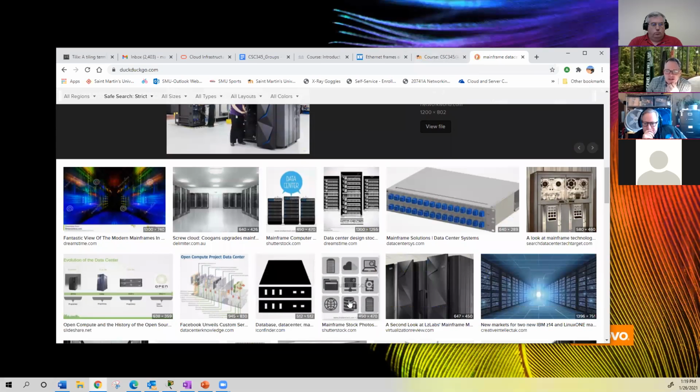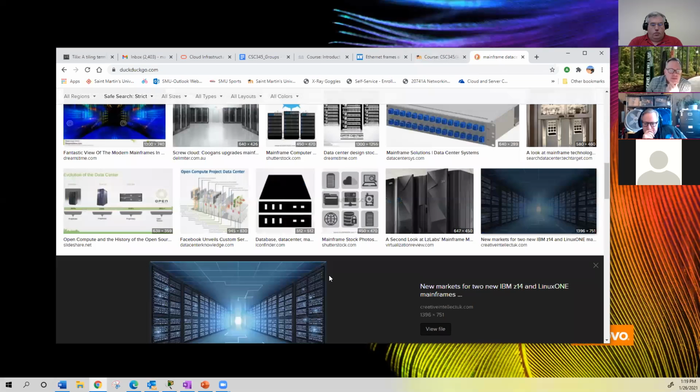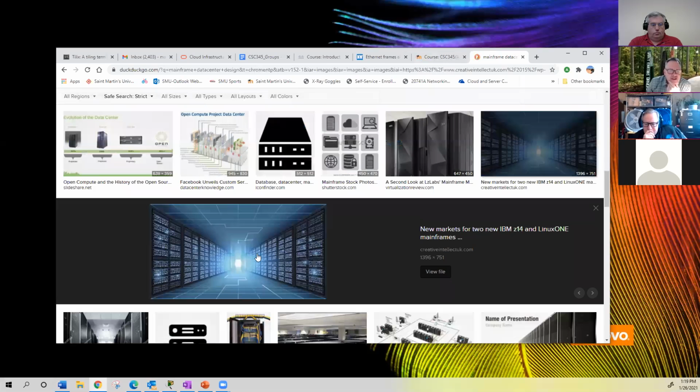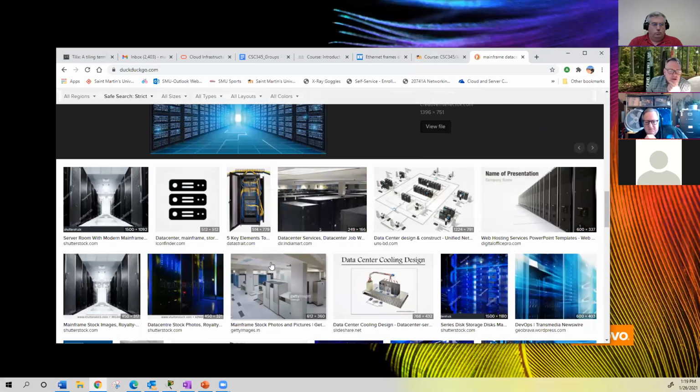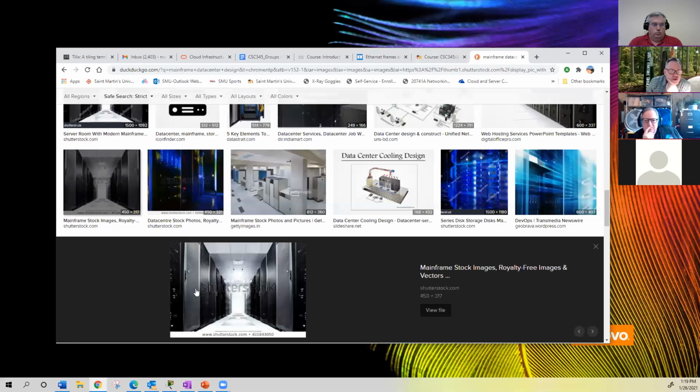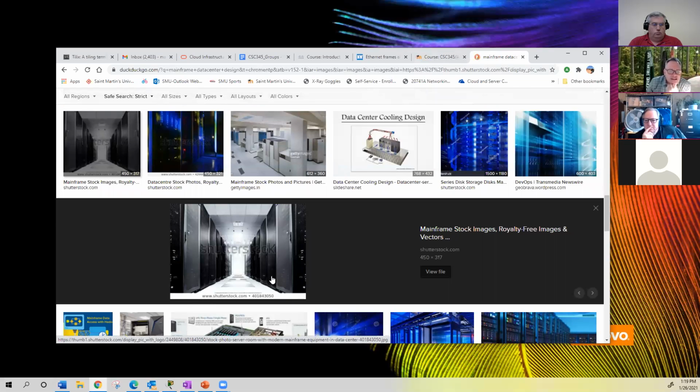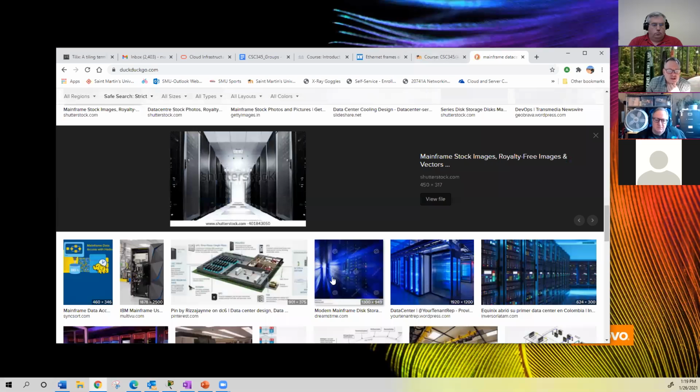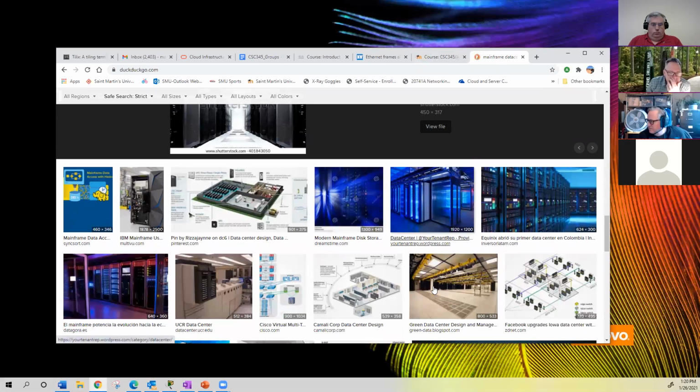More and more now, data centers look like this. They more have racks tightly butted up against one another in rows. And so in these rows, you have a hot aisle and a cold aisle. The cold aisle has perforated tiles where airflow blows up and then gets pulled into the front through the actual servers in the room. Now, with these, the isolation improves airflow because it doesn't allow hot air from the hot aisle to get back into the cold aisle.